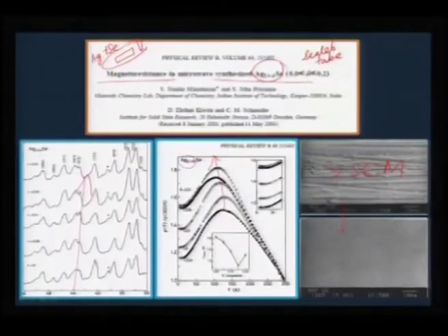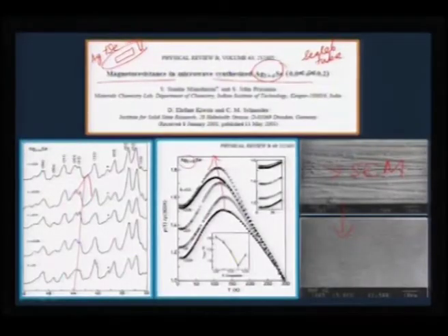So, as you would see, if you take an EPMA, electron probe microanalysis, of this to map only selenium distribution, just to see whether selenium has segregated or is uniformly distributed, all these minute spots that you see here are due to selenium mapping, which means selenium is equally distributed in this short period. So, silver selenide formation is a very classic example of doing both the synthesis and sintering together at the same time, which is a very versatile route to synthesize products.